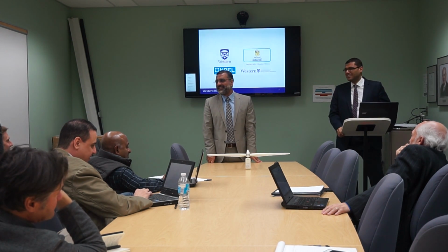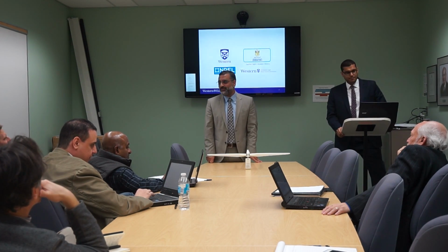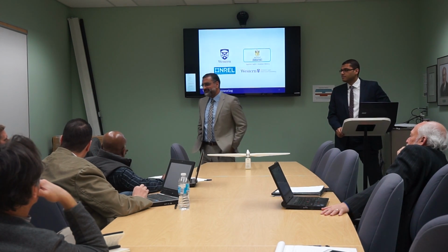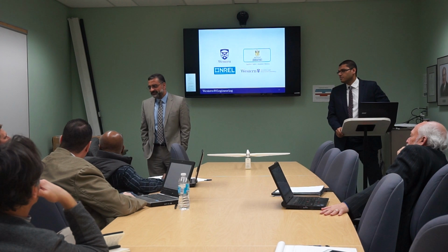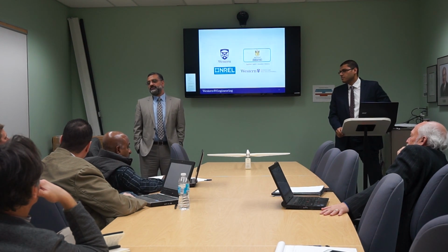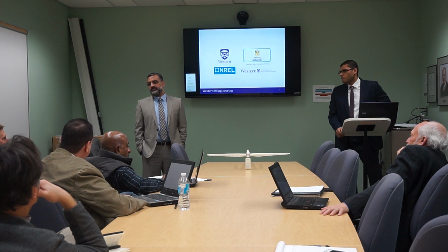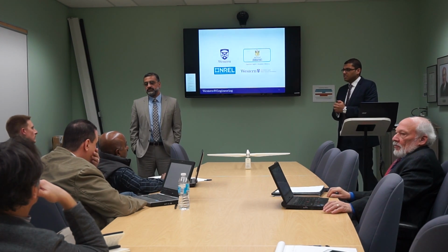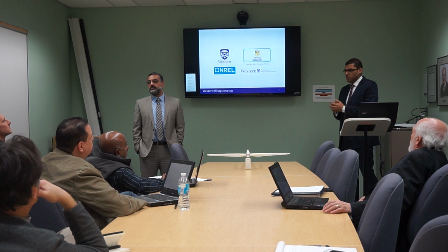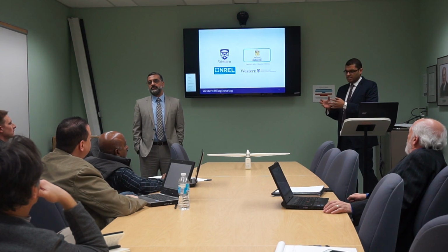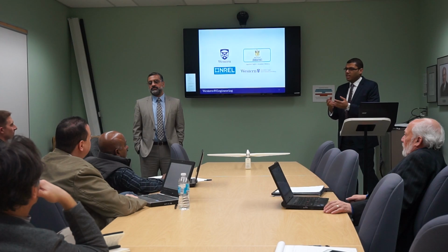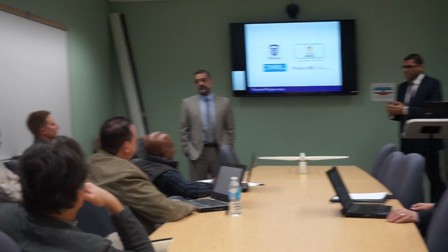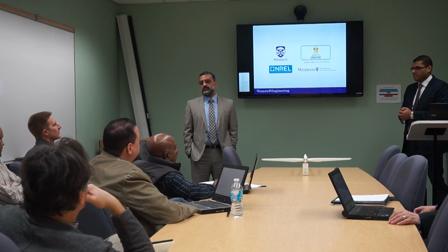40 minutes. Typically, examiners keep their questions to the examination period. One of the things I'm hoping to understand a little bit more, because I'm fairly ignorant, is how are wind turbine foundations currently designed? Actually, there is some equation presented by DNV codes. It's a really simple equation to present a P-Y curve. But as we all know, we cannot just depend on our empirical equation for something with billions of dollars. So we need to have some finite element analysis.